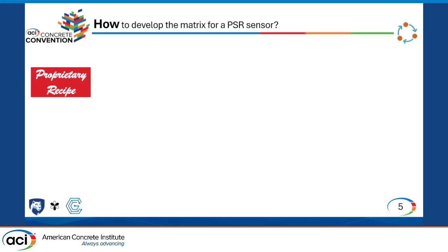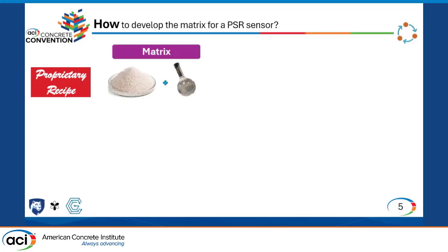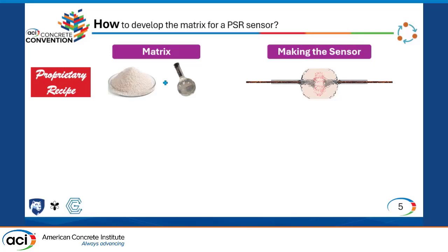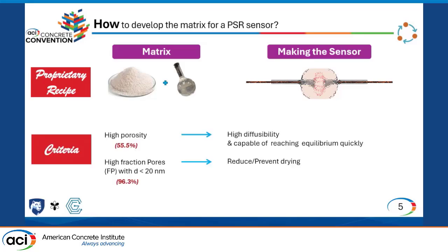I keep saying sensor and sensor, so what's our sensor? It's mainly a metakaolin-based geopolymer, and we try to make a robust system, part of which is the wiring and the size of the sensor, as well as the integrity of the structure, to provide a reliable measurement of the electrical resistivity. And we had to rely on some porosity properties. In terms of permeable pores, we needed permeable pores higher than 50% to ensure fast diffusibility, in addition to optimizing the sensor size.